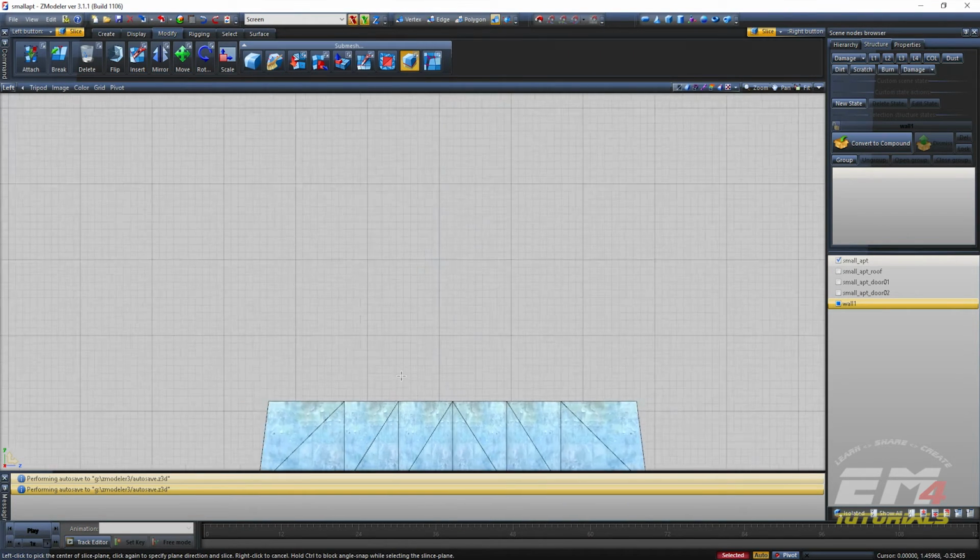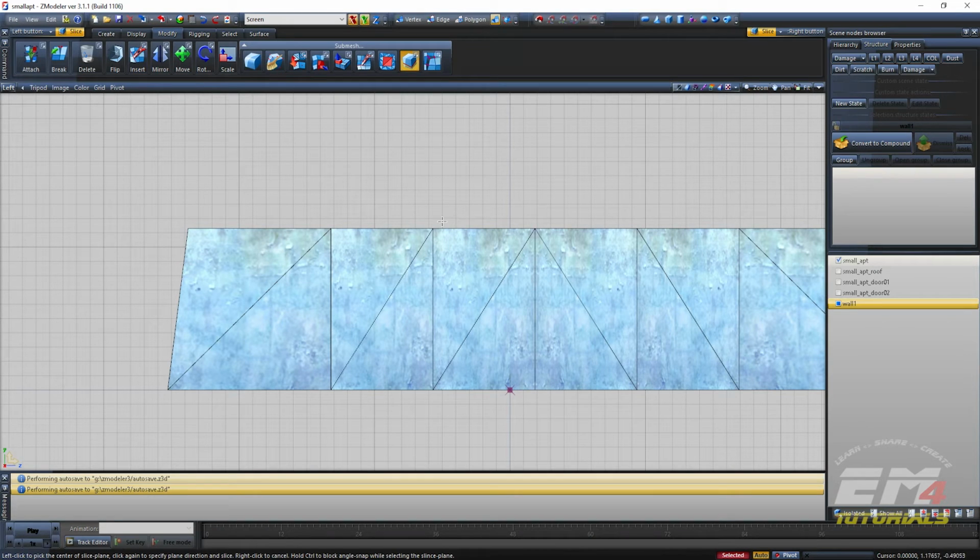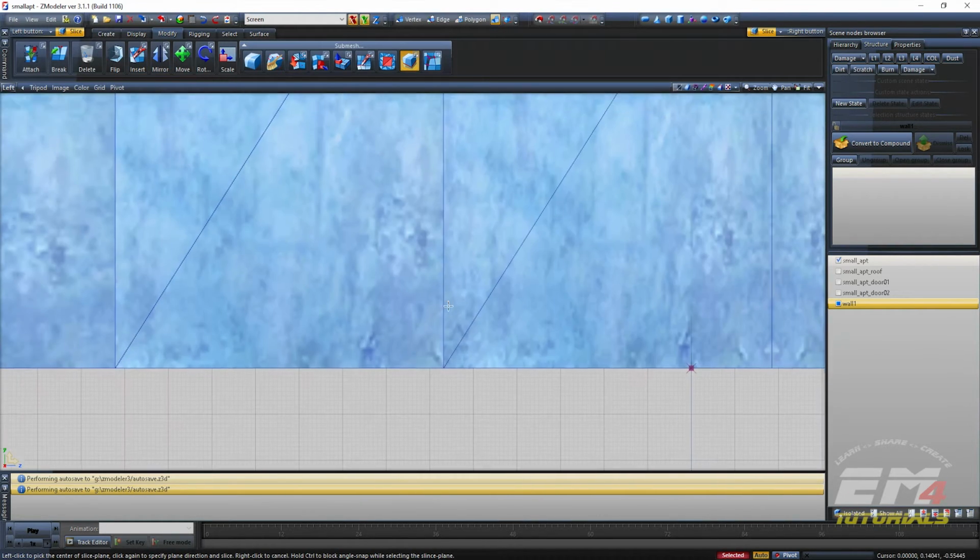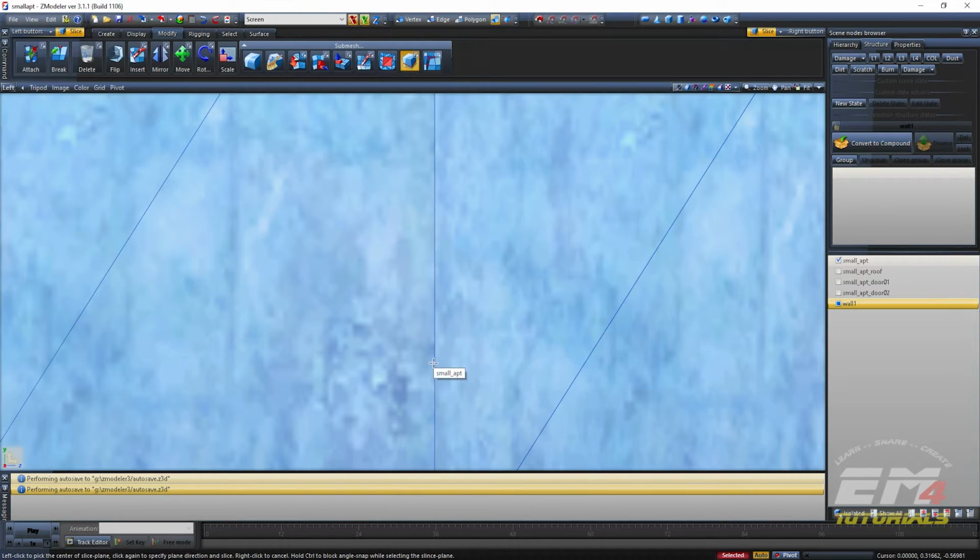All right. And if I recall correctly, I believe it is this edge right here that we are going to be slicing, or trying to create a wall directly from this perspective would be out of the screen and into the screen, right? So I'm going to take my slice tool, zoom in, and I am going to put these crosshairs right on that edge as best I can, just like that. And I'm going to hold my left mouse button down, and I'm going to make an upward motion like that, and you will see that red line pop up.